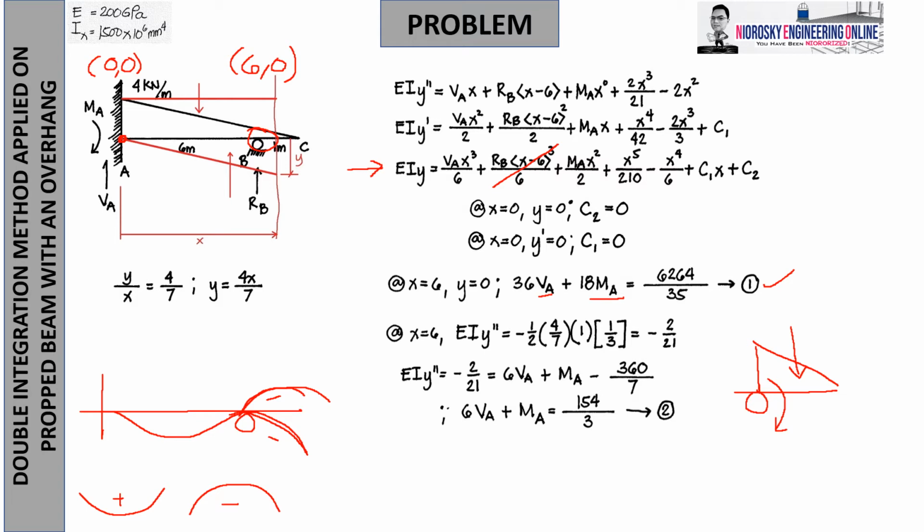That's why the load value here, if you trace it, is 4 over 7. How did we get that? You can substitute at x is 6. We can get that anyway. Going to the left, it is also 4 over 7. Or we can do it this way to make it easier, using the x measured from the right. This is 4, this is 7, and here we need the new y at a distance of 1. So y over 1 equals 4 over 7. So that's 4 over 7, the value in the nature of this load.